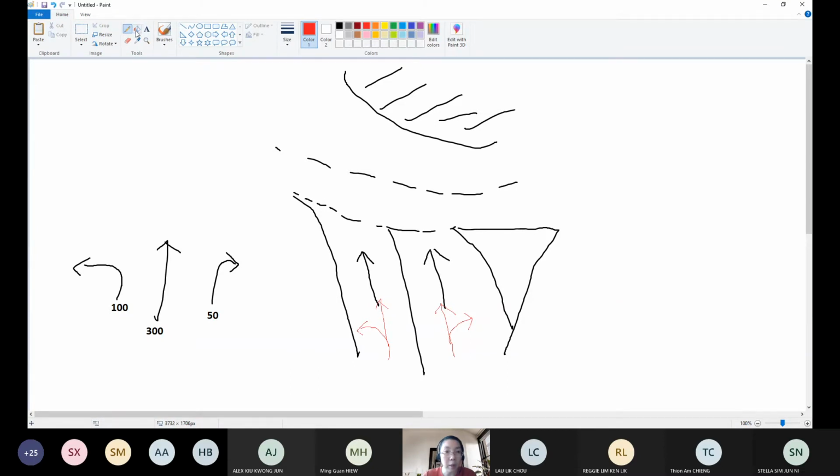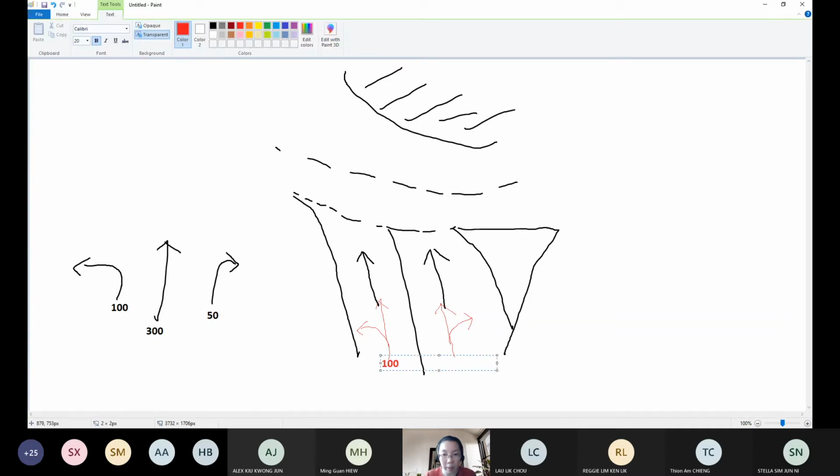All right. So that would mean for the entry flow, for the outer lane, the entry flow is 100 plus, we give it as 300 divided by 2 for simplicity's sake, which is then equal to 150 plus 100. So this is 250. And for this side, this is 300 divided by 2 for the through movement, and then plus 50. So this is 200